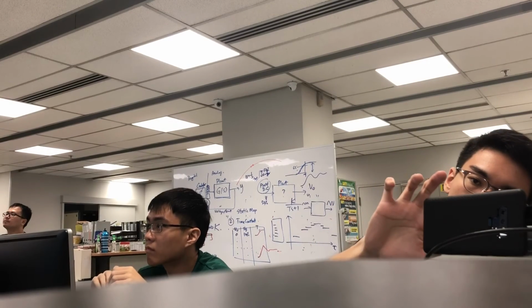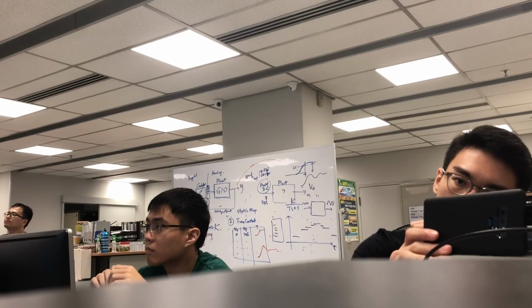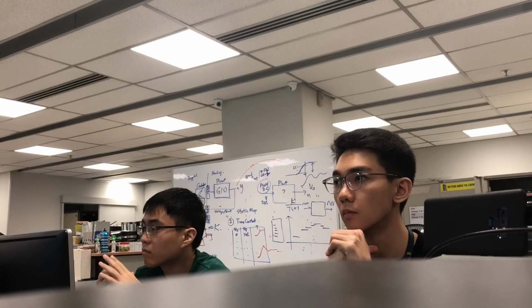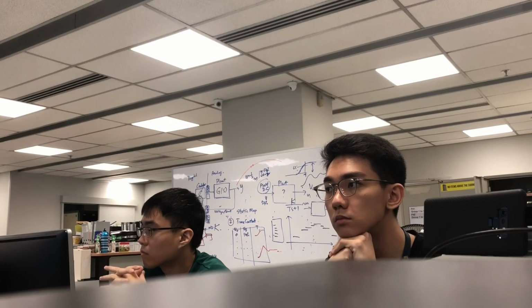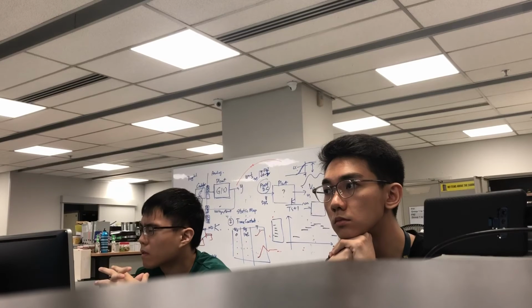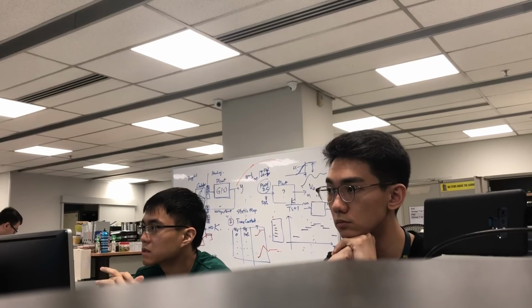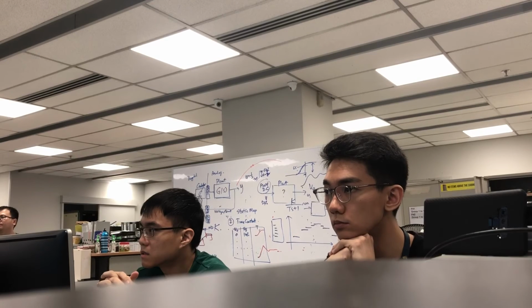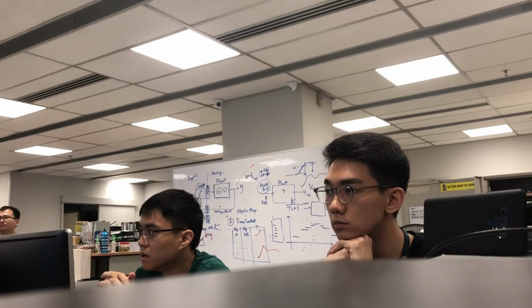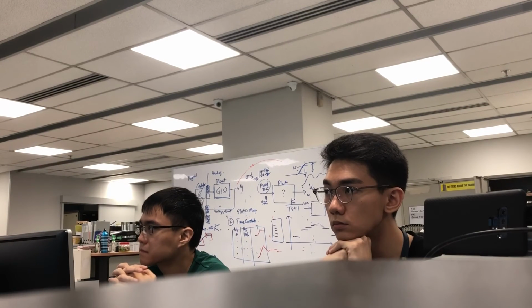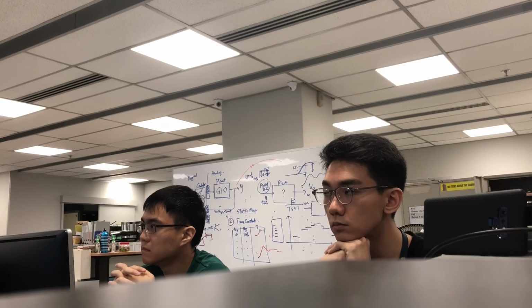I don't know how your circuit looks like, but in principle, it should be something like that, right? There's a DC-DC converter, there is an op-amp, and here is the PWM input, and then here is where John Chan gives you the solution. This is how you implement the compensator, and then you hook up the compensator, and the compensator somehow magically generates the required PWM with the required duty cycles. Okay? So part 2 is essentially replacing this part, your compensator, throw your compensator away, now do the microcontroller.